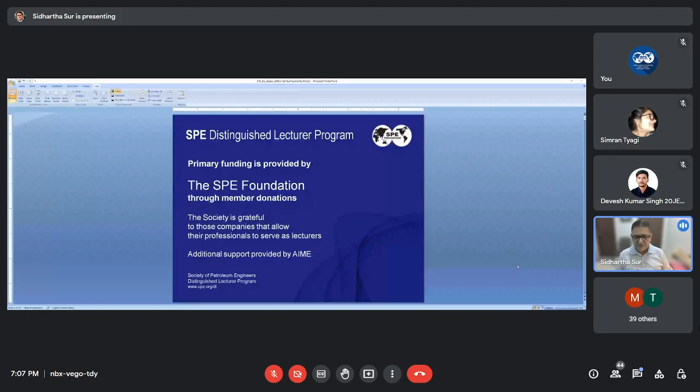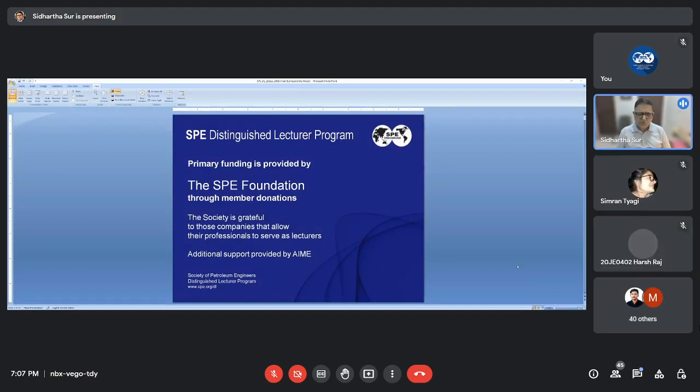So there is always an injector and producers. The injector injects the air to create the high temperature front, which is propagated radially outward, or maybe a distorted front in the direction of the producers, but it is sustained and propagated with continuous injection of air. So you can see this animation, injector and producer. There are several zones to this.